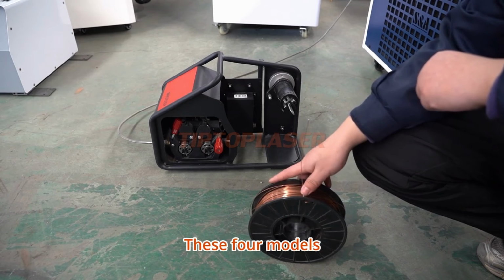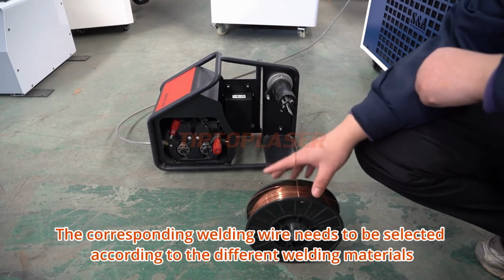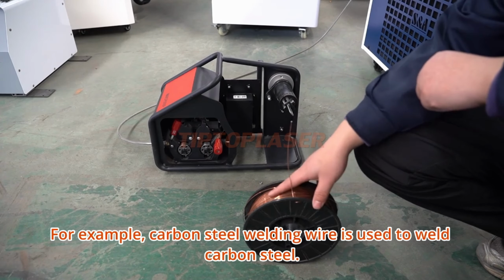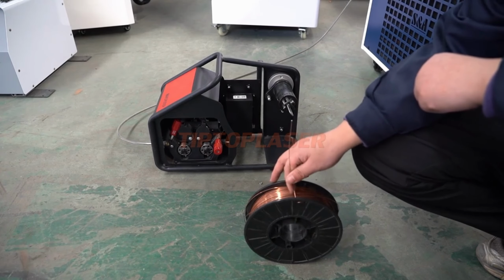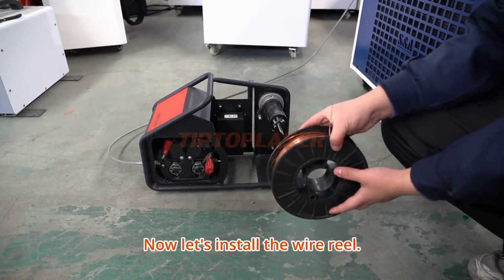These 4 models. Selection of welding wire materials. The corresponding welding wire needs to be selected according to the different welding materials. For example, carbon steel welding wire is used to weld carbon steel. Now let's install the wire reel.